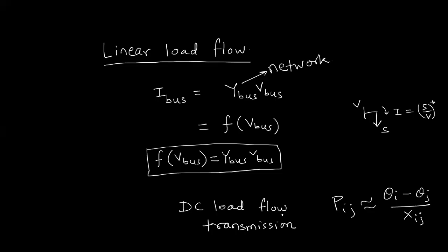So here we need some other formulation. We need to take a different set of assumptions and perform the linear load flow. In DC load flow there is only a single iteration; we are not solving it iteratively. The same thing we want to achieve for the distribution system. So let us see how to go ahead with the linear load flow for distribution systems.